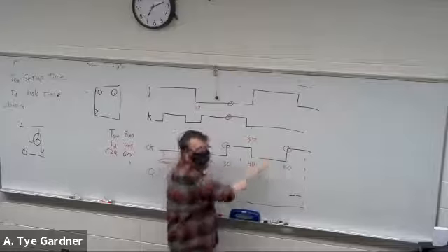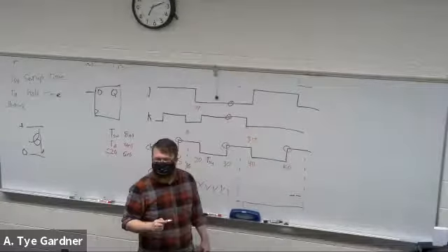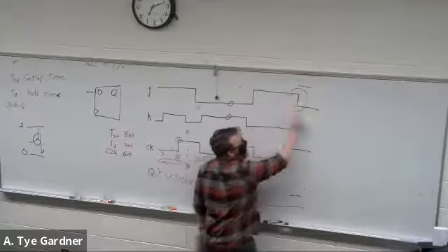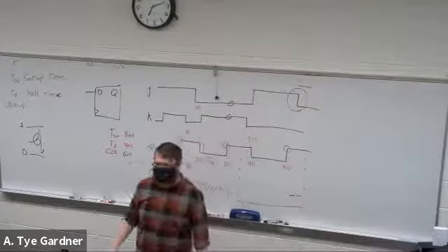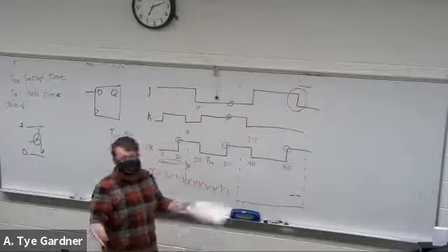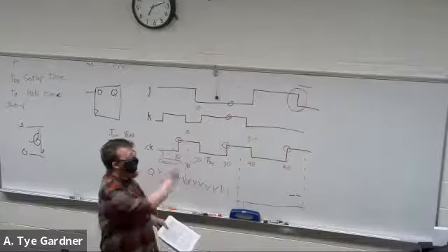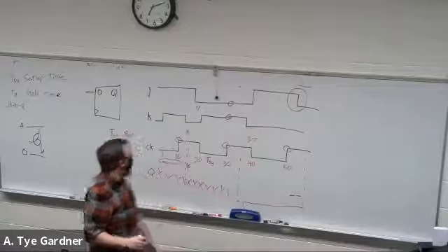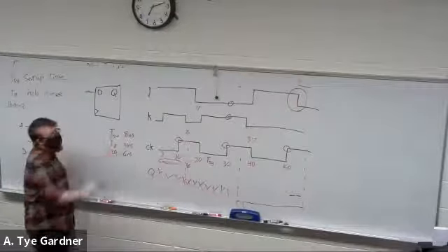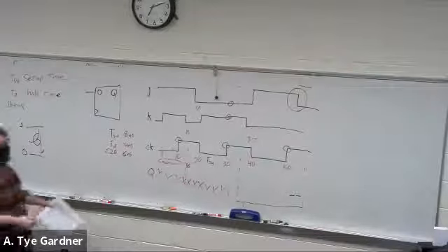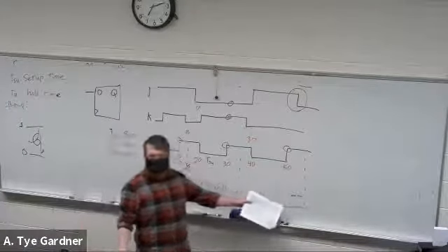Here, is the setup and hold time met? It's not. We're changing at the exact same time. Well, even if it was a little bit over, it doesn't help because I need to be 4 nanoseconds over. Right, because that's my hold time, is 4 nano. So if I don't meet these setup and holds, I'm in trouble, because I don't know what it is. So there's only this really short window that I actually know what it is.